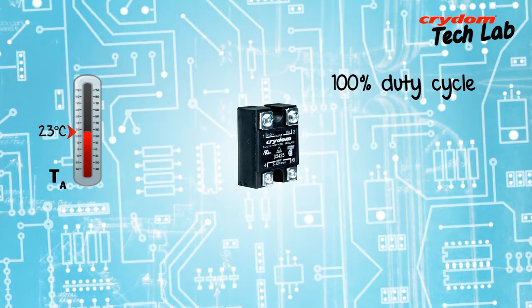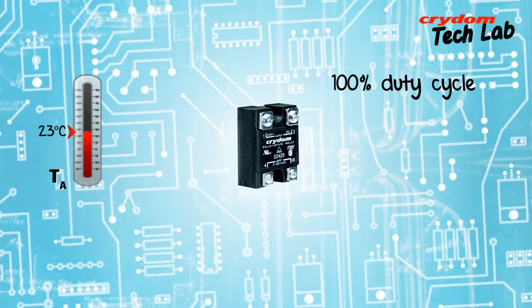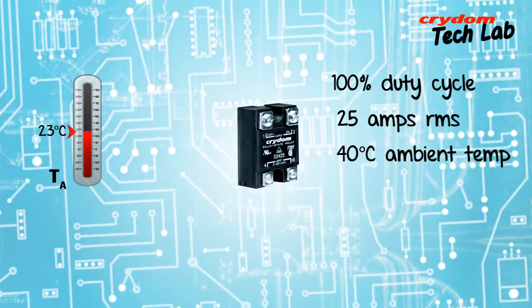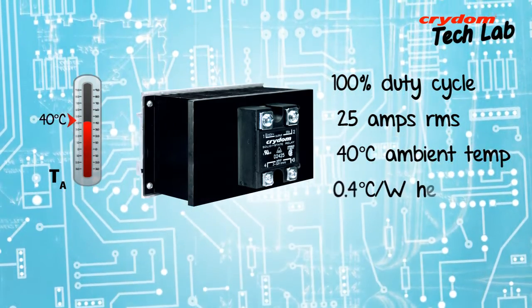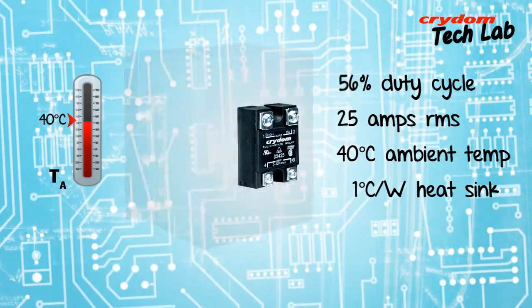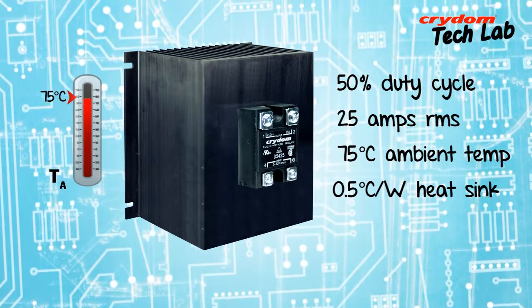For example, this Crydom D2425 SSR is rated for continuous 25 amps RMS load current in a 40 degrees C ambient when mounted on a 1 degree C per watt heatsink. But what if the conditions of application for this SSR are different than these parameters?